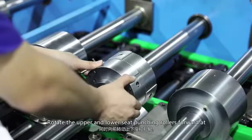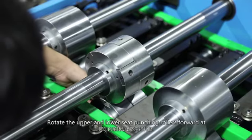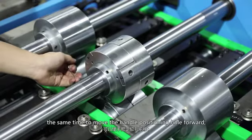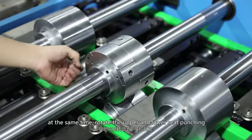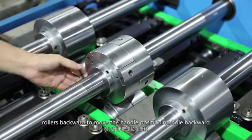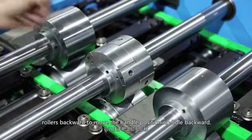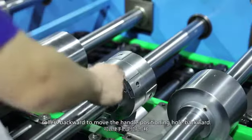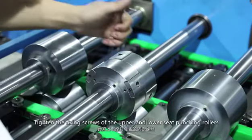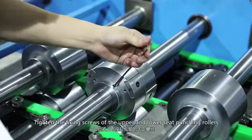Rotate the upper and lower seat punching rollers forward at the same time to move the handle positioning hole forward. At the same time, rotate the upper and lower seat punching rollers backward to move the handle positioning hole backward. Tighten the fixing screws of the upper and lower seat punching rollers.